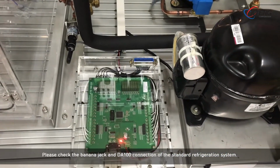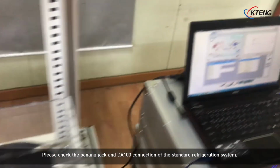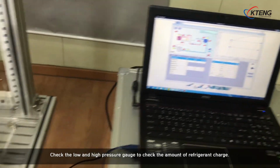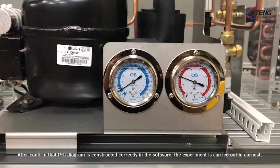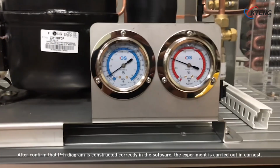Please check the banana jack and DA100 connection of the standard refrigeration system. Check the low and high pressure gauge to check the amount of refrigerant charge. After confirming that the p-h diagram is constructed correctly in the software, the experiment is carried out in earnest.